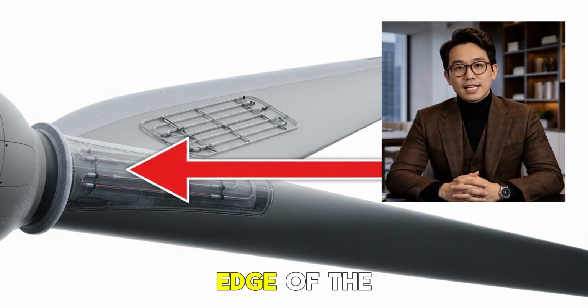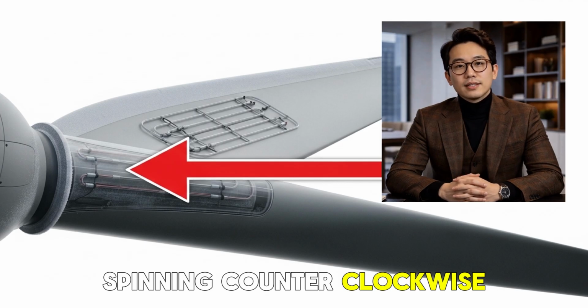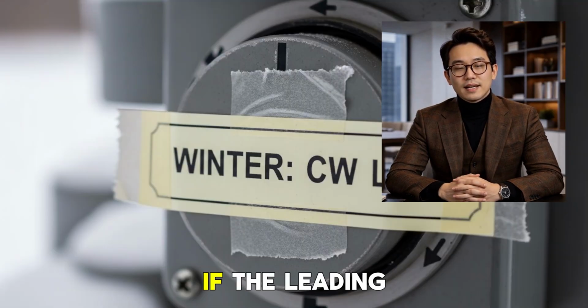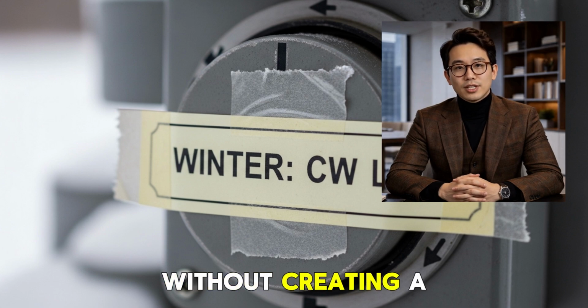If you can see the leading edge of the blades moving from your right to your left, the fan is spinning counterclockwise. This is summer mode. It pushes air straight down, creating a cooling breeze. If the leading edge moves from your left to your right, the fan is spinning clockwise. This is winter mode. It pulls air up and circulates warm air down along the walls without creating a direct